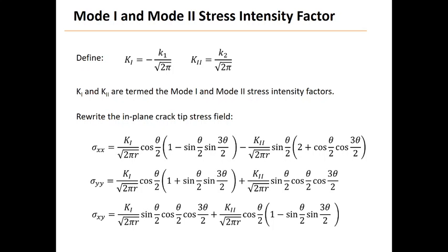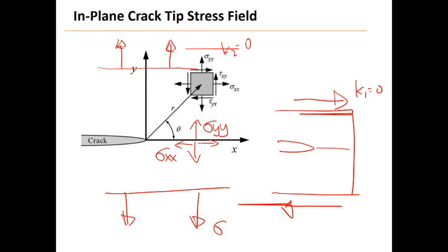So we applied a certain amount of tension in the Griffith crack, right? For example, this one right here, we apply some tension stress on a plate with a crack. Let's say that you apply stress sigma, and it's going to intensify the stress. Just like the stress concentration factor, you're going to intensify the stress, and K gives you the value of how much intensification of the stress happens around the crack tip, right? So K relates whatever stress is being applied to the stress right in front of the crack tip, okay? And that is the stress intensity factor.